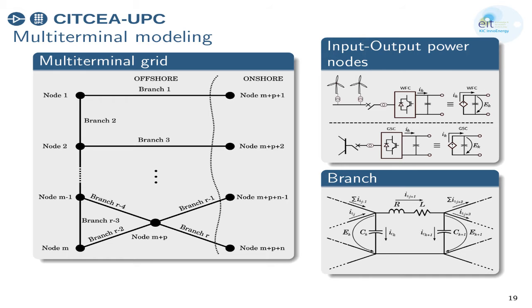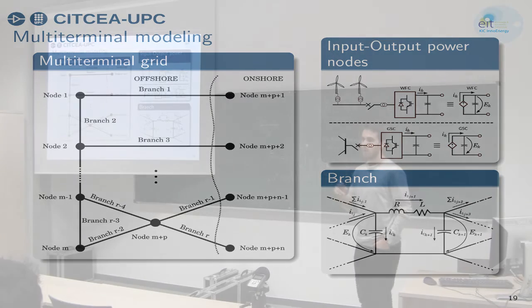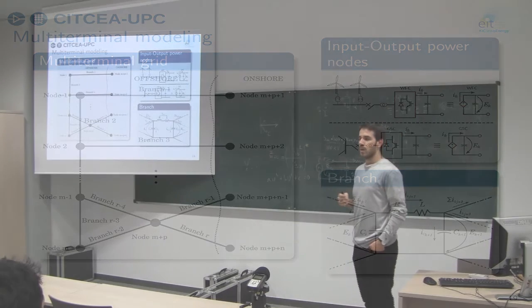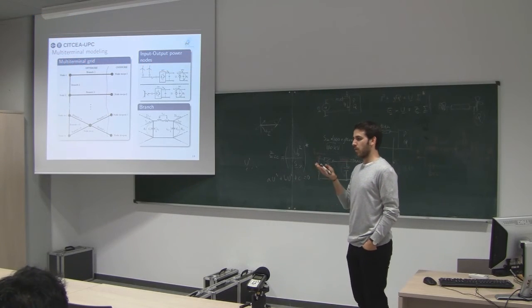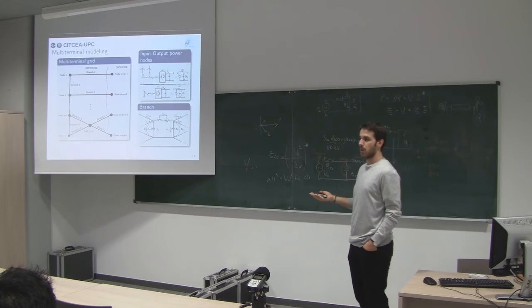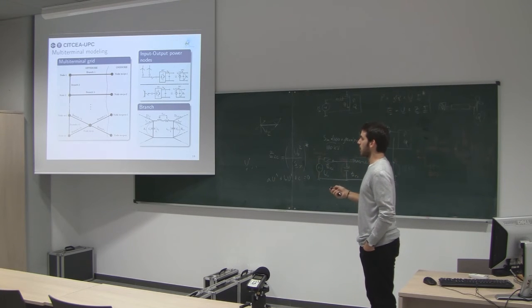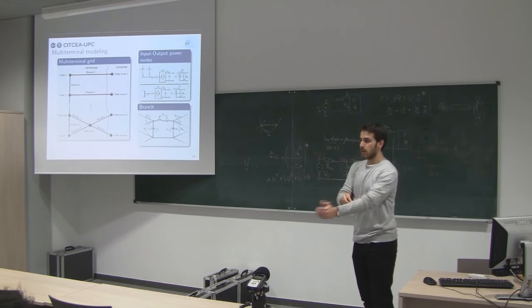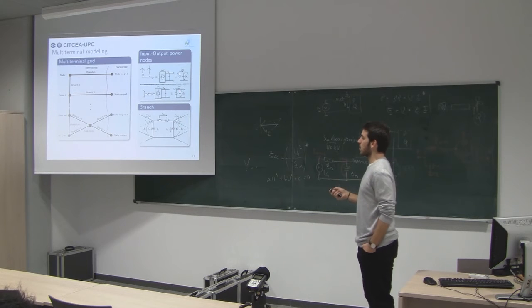This is what we have. We have the wind farm, and we were modeling them with just a simple current source. So they are essentially current sources. They are injecting some power, and if you have a wind farm, for example, of 400 megawatts, it won't exceed those 400 megawatts because of its maximum capability, of course. So we can model them like this. And regarding the grid side currents, we are modeling them on the DC side, not on the AC side, with a DC current source, of course.